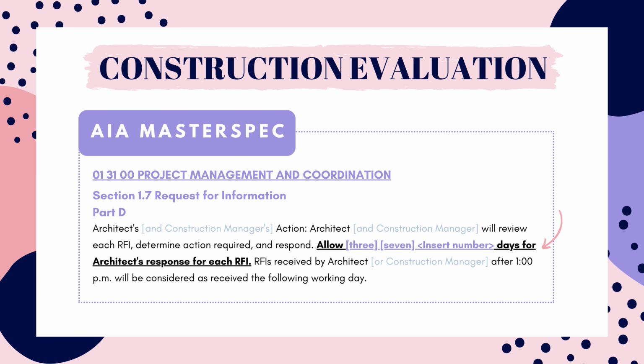I believe at our firm, we typically have 10 business days to respond to RFIs and submittals. We try not to use all of that time, but some RFIs can be complex and may require a lot of research or coordination between subconsultants, manufacturers, or possibly the contractor. Also, when the contractor sends you an RFI, they will typically include a response date of when they would like it back. That date may be a critical date, meaning that if the response is sent later, it could delay the project. So always do your best to respond sooner rather than later and communicate with your contractor to make sure you know which RFIs are critical.